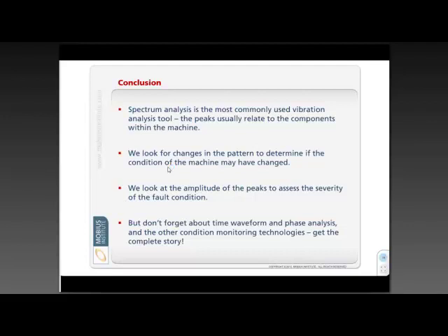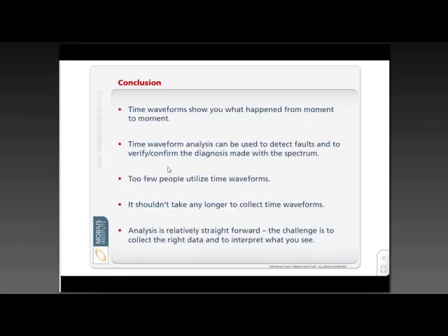But we should think about other sources of vibration, as in from the time waveform and phase and so on, and we should use other condition monitoring technologies to get the complete picture. Look at the oil if you can, use ultrasound if you can, use thermography if you can.